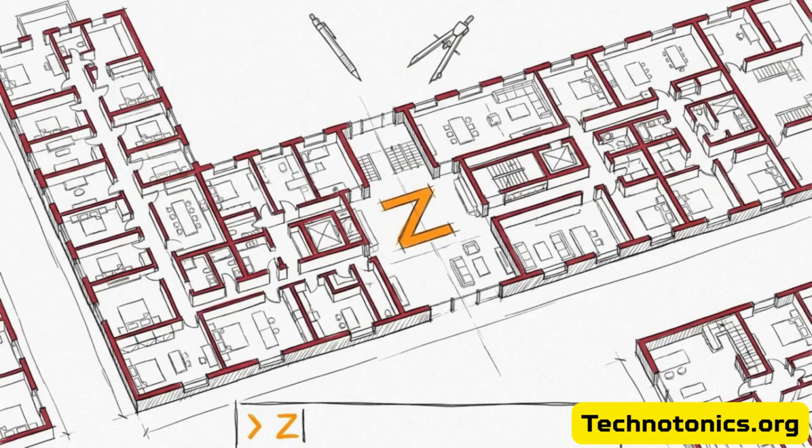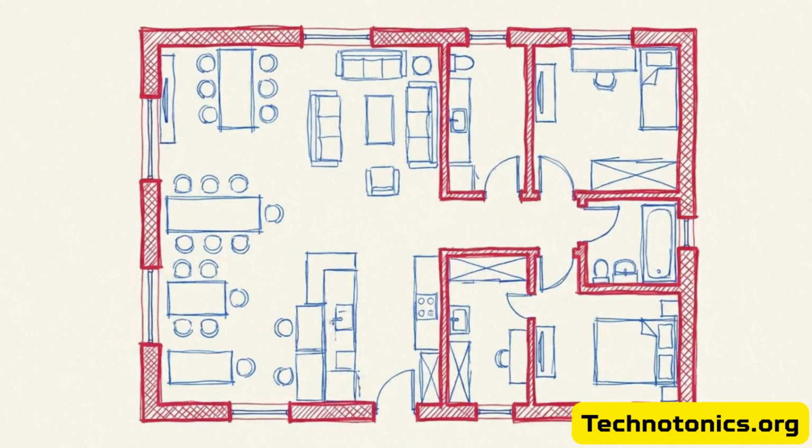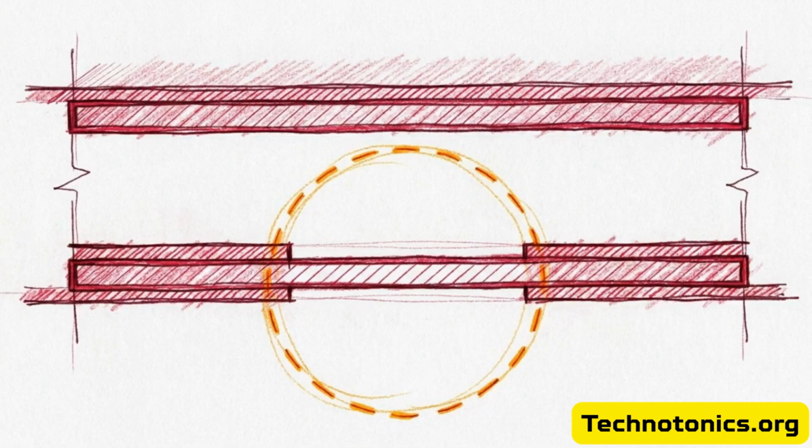As your layout expands, type Z to zoom or P to pan. These navigation mechanics keep your workspace centered and visible as the design grows. Establishing organizational layers early prevents your drawing from becoming a tangled, uneditable mess as details grow.